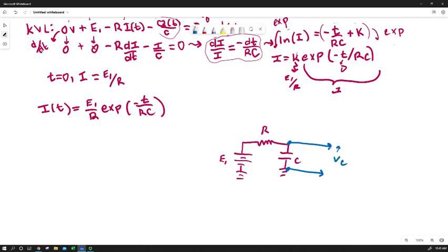We'll hook up our scope probe to this point right here, and it'll automatically measure between that point and ground, as our oscilloscope will, because it's grounded through our voltage source, which in the case of our USB oscilloscope will be through the ground of the computer that's driving it. So this will be a function of time. We'd like an expression that matches this so we can compare our calculations to what we're measuring.